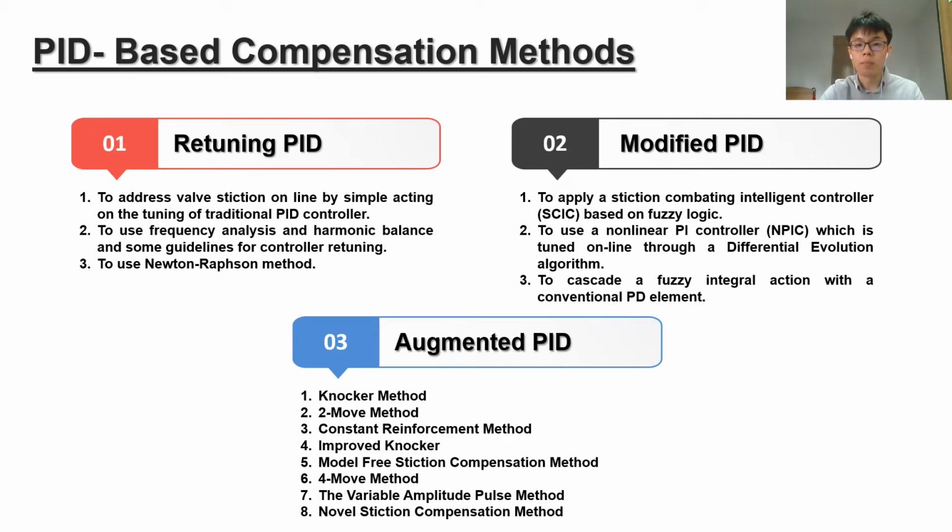The points listed below the modified PID are the methods that have been found. Modifying the PID controller without using any additional components would be a good option for the industry to solve the non-linearities problem on behalf of valve stictions, because it can reduce the overall maintenance cost.